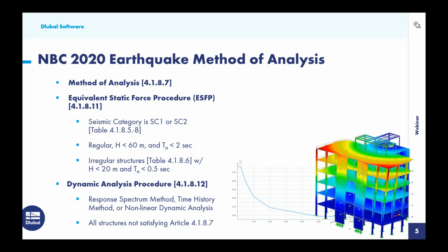Then we have the dynamic analysis procedure in 4.1.8.12, and this includes the response spectrum method, the time history method, or the nonlinear dynamic analysis. This should really be applied to all structures that do not satisfy the simplified requirements set forth in Article 4.1.8.7. For today, we'll move forward with the response spectrum method for our structure.